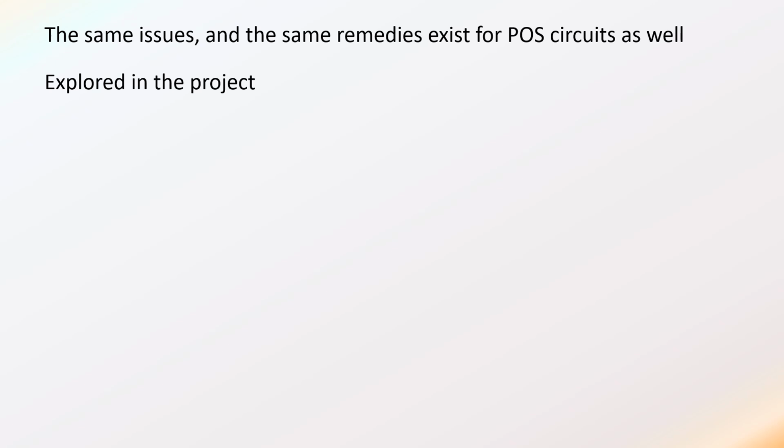And then if you really need to remove the possibility of a glitch from an output, you can do that by adding unnecessary redundant logic gates to the circuit. So you're making the circuit less efficient by adding extra resources, but in doing so, you can remove the possibility of a glitch forming. Again, that's a fairly rare thing to have to do, but it can be done.